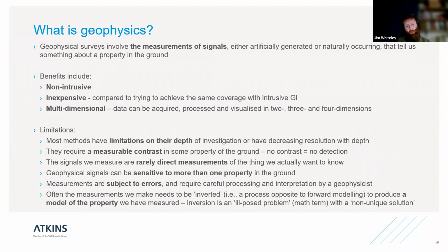I think one thing that's really overlooked is that, so we obviously understand from a physical perspective what it is we're measuring, but actually there are lots of errors that are introduced into geophysical surveys as well. And those errors can come from measurements in the field. They can be from poor practice, or they can be just from difficult ground conditions, but they can also be introduced in the modeling stage.